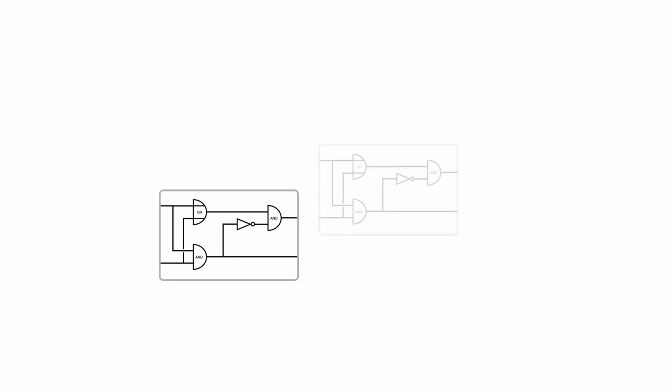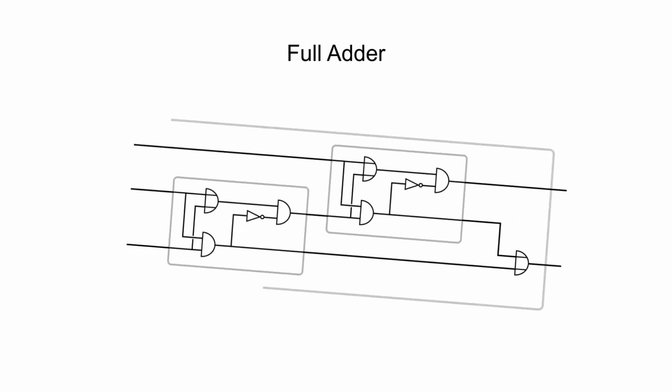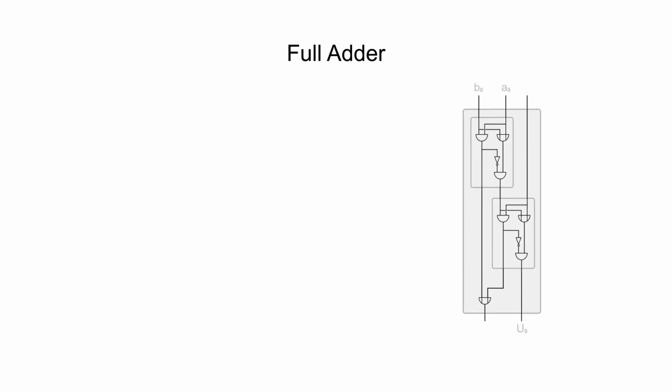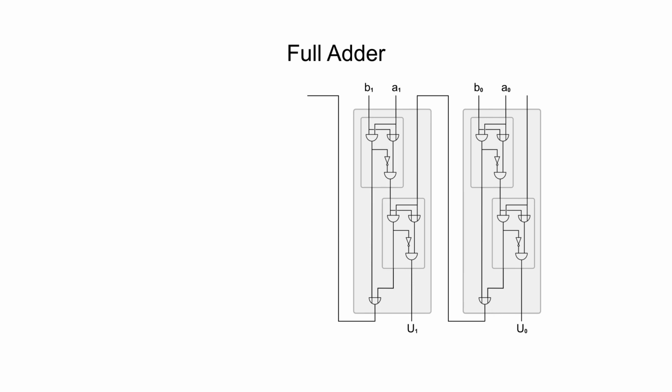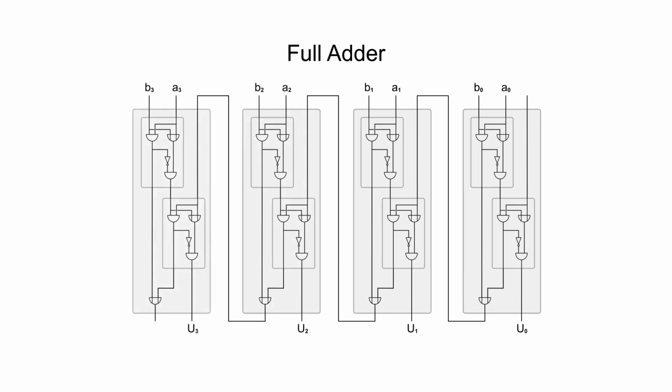For binary numbers with several places, where one has to process the carry place digit of the previous addition, the so-called carry old, one needs a circuit which has 3 inputs and 2 outputs. For this, one uses a so-called full adder. One of the inputs is used to take into account the carry of a preceding calculation. Placing multiple full adders in series allows for the addition of binary numbers with more than one digit.